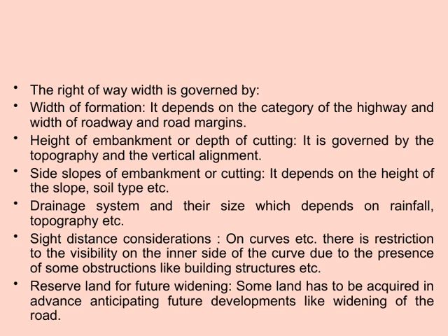On curved sections or areas with obstructions like buildings, visibility can be restricted on the inner side of the curve. Ensuring adequate sight distance is essential for safety, which sometimes means widening the right-of-way in these zones.